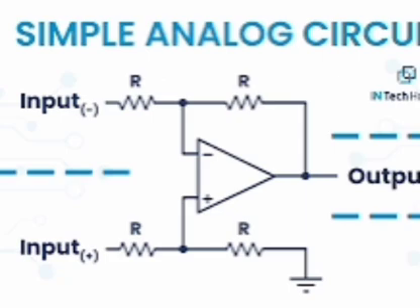Characteristics: input resistance of CB configuration is very low, 40 ohms, whereas input resistance of CE configuration is 50 kilo ohms, low. Input resistance of CC configuration is 750 kilo ohms. Output resistance of CB configuration is very high, 1 mega ohm. Output resistance of CE configuration is high, 10 kilo ohms. Output resistance of CC configuration is low, 50 ohms.